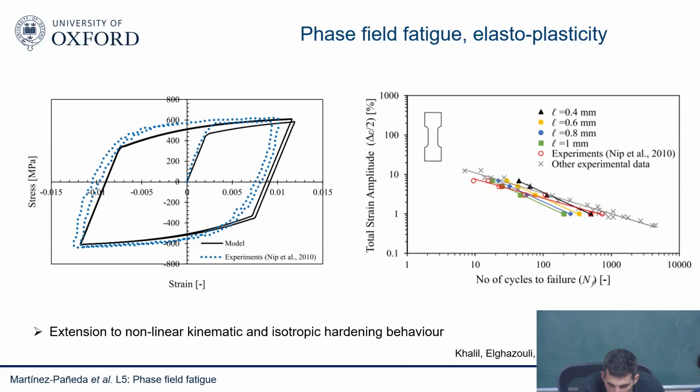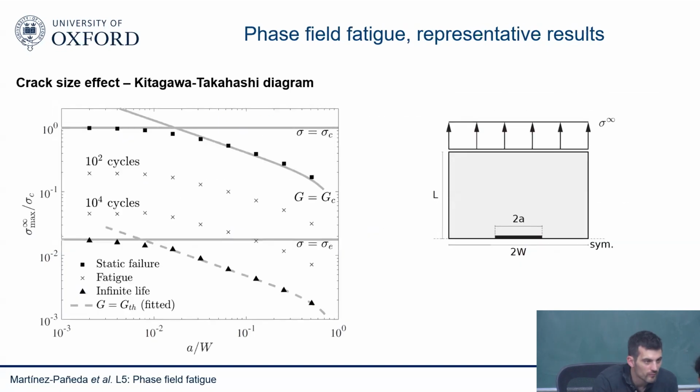Slide 24. You are taking multiple cases, right? Yes, changing the crack size. Or we can do it like this: we already know the crack will propagate. So we have one geometry where there is a fixed a. Once the crack propagates, automatically a will change, and accordingly the sigma will also change. You're saying instead of running multiple simulations, just take the same simulation and see how it grows with the number of cycles.